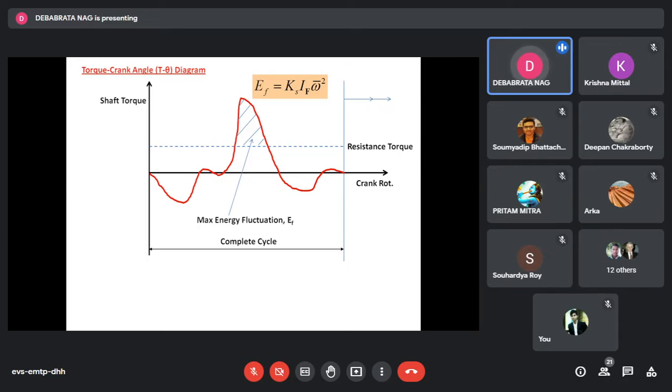But in India, the alternating current frequency is 50 hertz. And 50 hertz means that your engine needs to run at 3000 RPM. Correct? So you need to maintain a balance. Actually, all the time it will not be accurately running at 3000 RPM or 50 hertz.